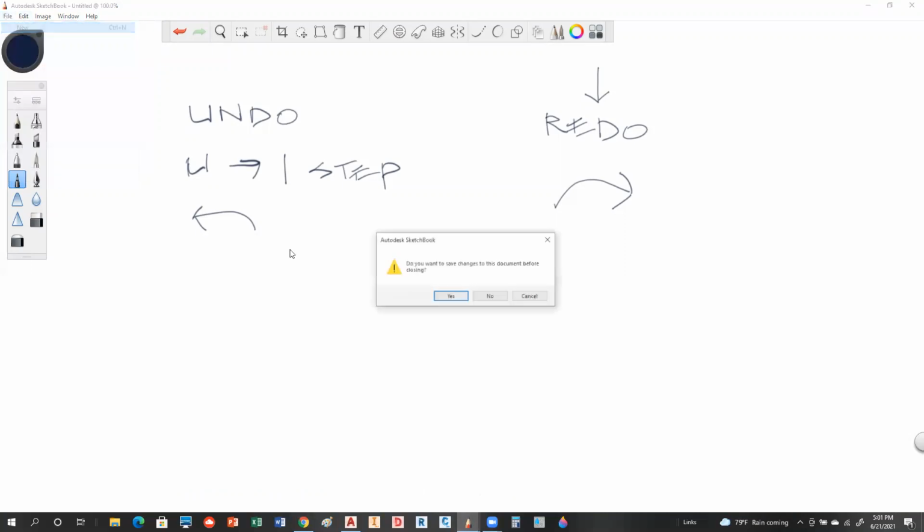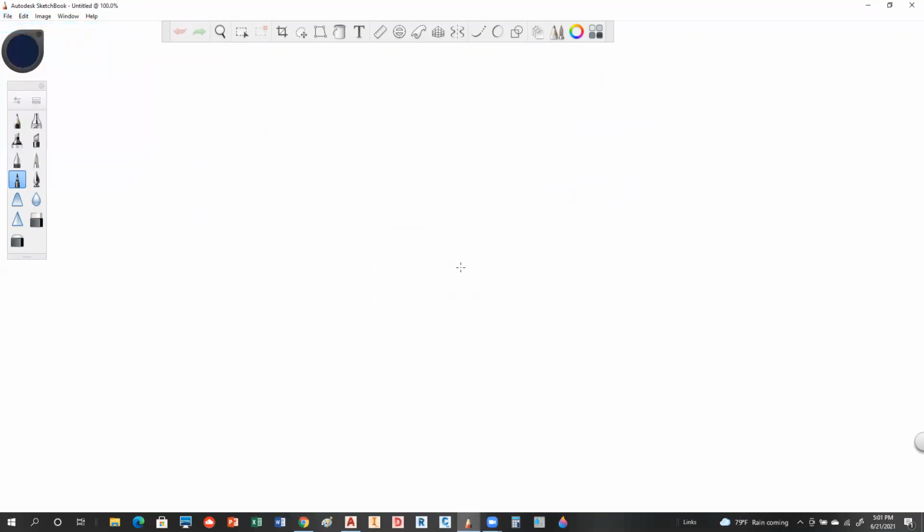And copy will be very similar to move, okay? So once I explain move, then we'll see how copy works. First off, you need to understand that the alias for move is M. This is really convenient because that allows me to generate it really quickly.